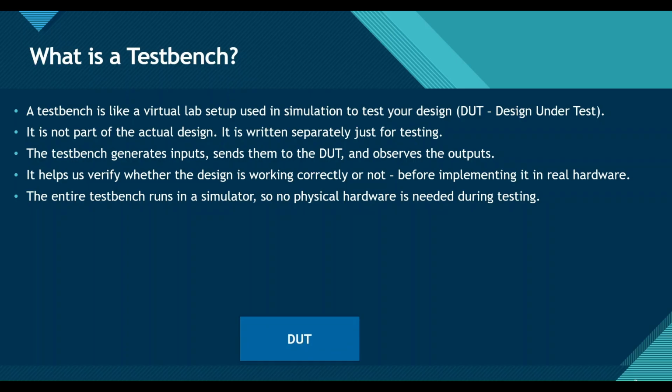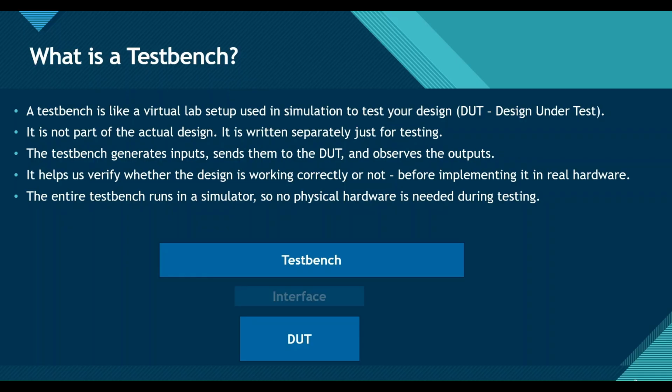Assume this is the DUT. DUT means design under test. This is our actual design. After that, we will write the testbench separately. We connect this testbench and the DUT using an interface. By connecting using the interface, we will verify our DUT using the testbench.